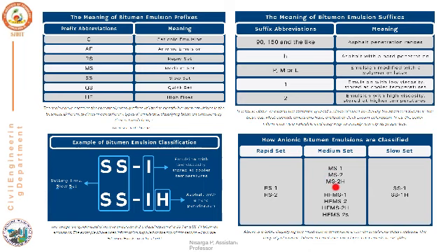Similarly, MS2H. MS for medium setting. Number 2 here indicates emulsion with high viscosity stored at high temperature, and H here indicates the asphalt with hard penetration. So this is how we can identify the particular type of bitumen depending upon the nomenclature. With this, I'll conclude the types of bitumen, and in the next session, we'll see the cutback and the types of cutbacks that are used in road construction work.